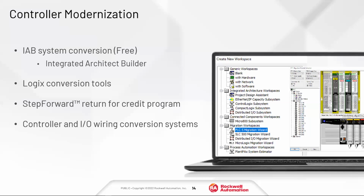And essentially what you do is you build your existing system in Architecture Builder, and then with a few clicks and a few decisions, you can build up a new bill of material, whether it's ControlLogix for a PLC5 migration, or a CompactLogix for a SLC migration, or even a Micro800 bill of material for a MicroLogix migration.